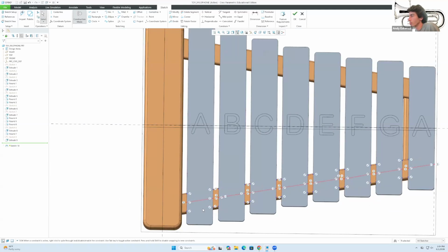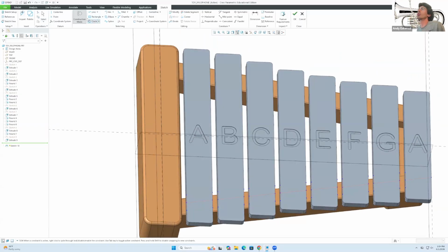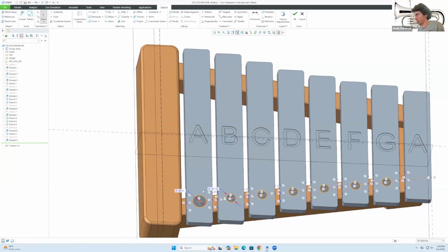So what can we do based off from this? Well, I'm gonna go here to circle. I'm just gonna place a bunch of circles. So you see that all of these are the same, so then I'll make it, they're all equal radius, which is fine. But now let me make that one and that one equal too. Okay, I will go here to equal, select that, very good. So now let's make it 20.